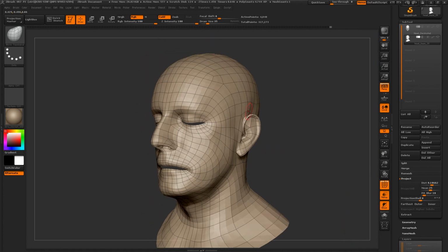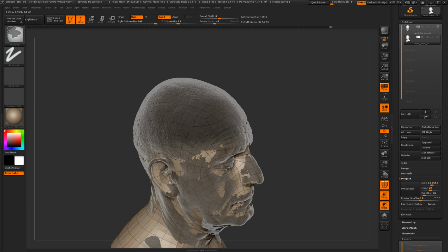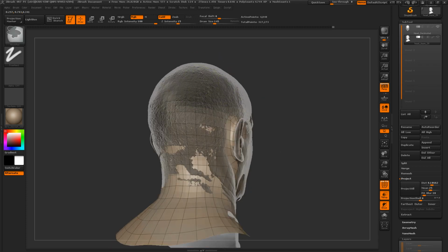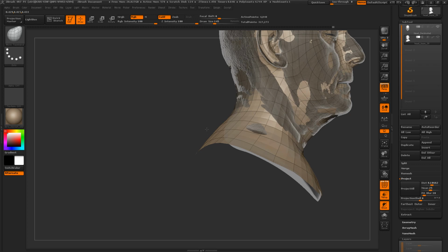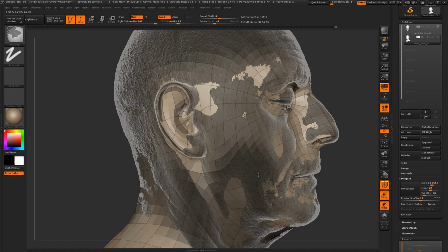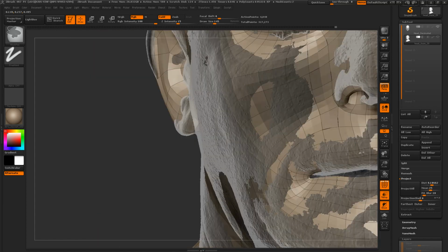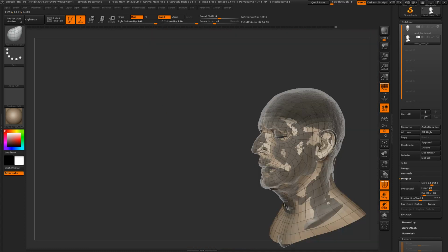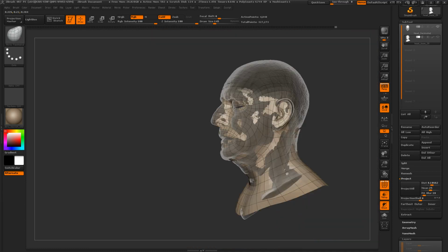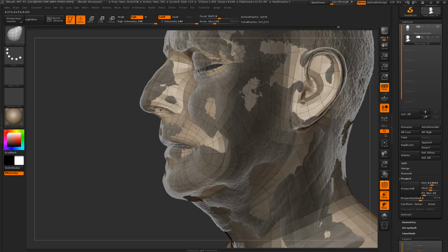Meanwhile, let's start reprojecting some stuff from the high poly. So once again, we'll start from the general and work towards specific areas. Start with the biggest, flattest planes and go towards things that have much tighter detail, like the eyes, the nose, the ears, etc. In this case, we're lucky because we now have more geometry. That means we can project onto much more tightly controlled areas when we mask them off. This is much higher res, and that's nice to work with.